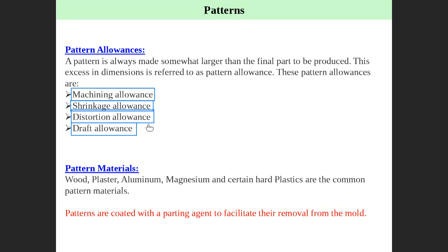What happens, Saud, if the riser does not work for any reason? If a collapse happens, if the riser doesn't work for any reason, you design it perfectly, but when we do the casting the riser is not working, what is the solution? What do you think will happen? We have to scrap this material, right? Then in this case, it's better to make a double factor or double safety. Put some shrinkage allowance and a riser as well. If the riser works, we didn't lose anything, fine. If the riser doesn't work, then shrinkage allowance can solve the problem. Did you get it? Yes, thank you.